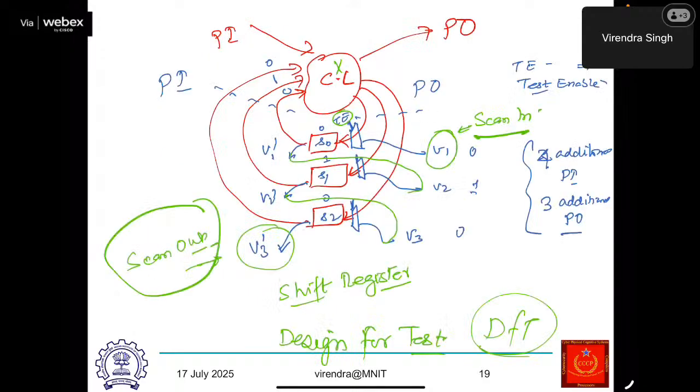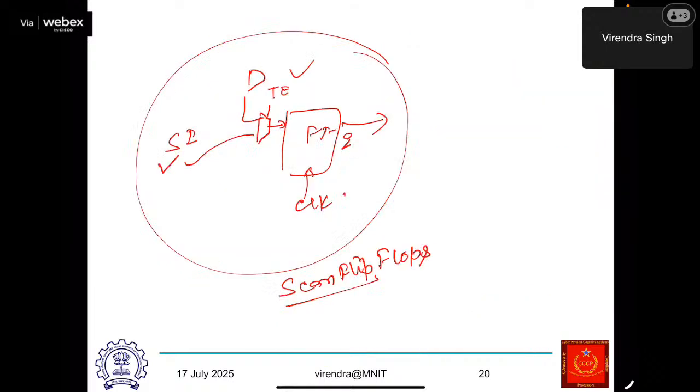So now the question here is, I can test this combinational logic, but what about these flip flops, the storage elements? These are storage elements, like a memory element. So shouldn't we need to test them? I need to test them, and you can easily test them by marching a sequence of 0011 0011 0011. It will show that it can retain the value 0, and it can retain the value 1, or it can transition from 0 to 1, or from 1 to 0.